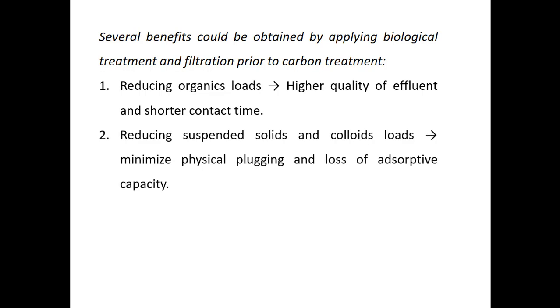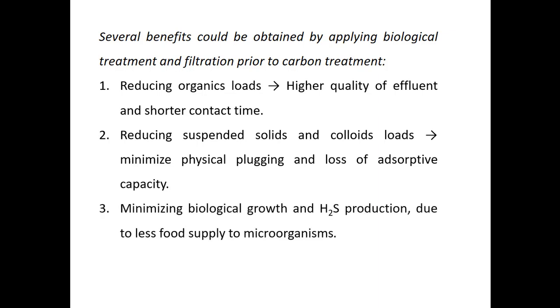Okay, and the second thing, we reduce the suspended solids by filtration. And we reduce also the colloid loads. This will minimize the plugging and the loss of the adsorption capacity of the activated carbon. So we will have longer working time, or longer active time, of the activated carbon. And the third reason is that when we reduce the biological growth and the H2S production, this will be minimized due to the less food supply to microorganisms, and consequently the process will be more efficient. So that's why we apply biological treatment and also filtration before we apply the carbon treatment.